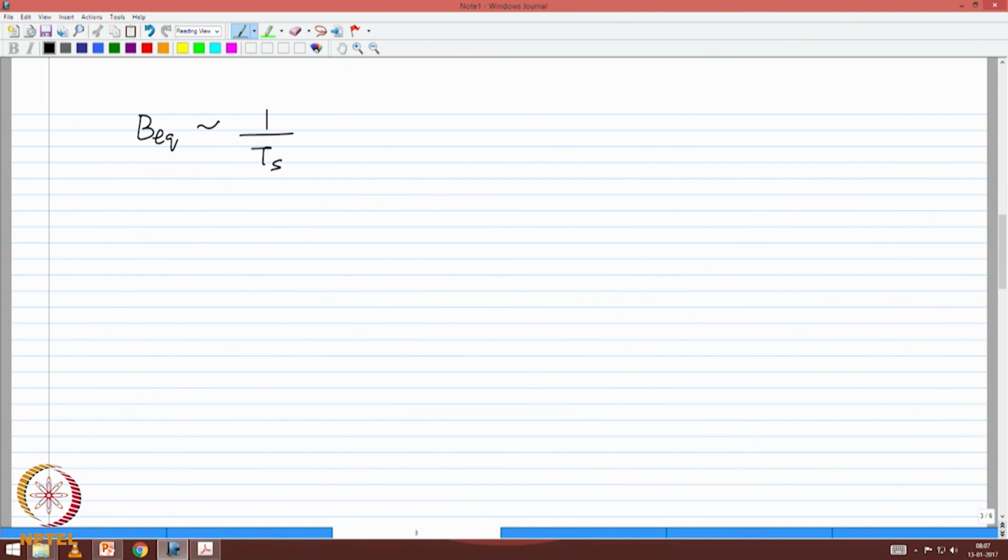Bandwidth is proportional to the symbol rate when you use the square root raised cosine as your pulse shape at the transmitter and receiver. Okay. So, for us, EB by N naught, that is a quantity that is theoretical but not very practical, can be related to a very practically measurable quantity PS by Pn.